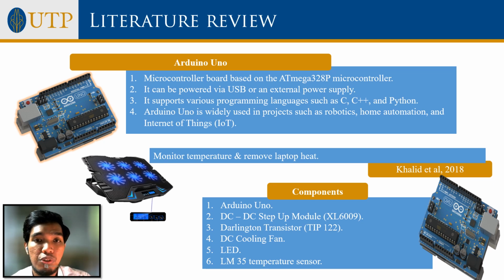One interesting project involving Arduino Uno and a laptop cooling fan was developed by Khalid in 2018. Khalid used an Arduino Uno to control the fan speed and monitor the laptop's temperature using an LM35 temperature sensor. The components used in the project also included a DC-DC step-up module XL6009, Darlington transistor TIP122, DC cooling fan, LED, and LM35 temperature sensor.